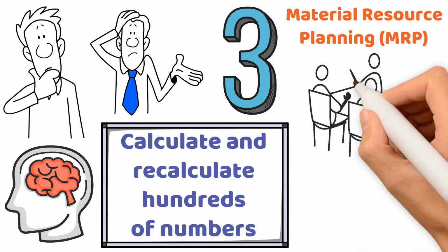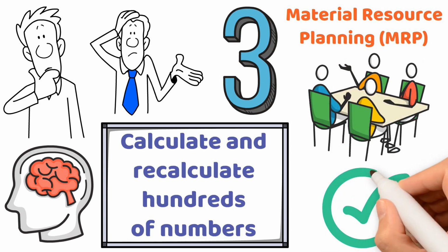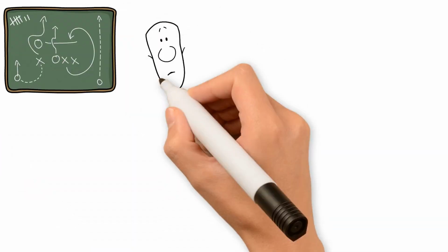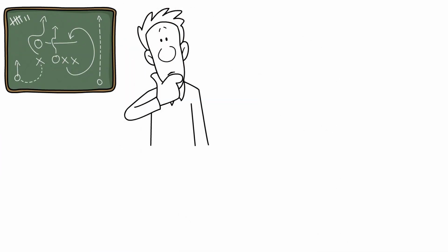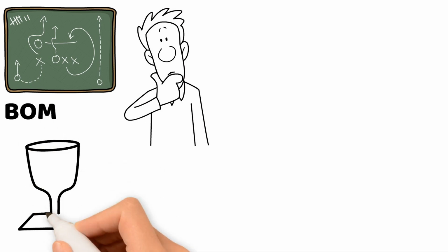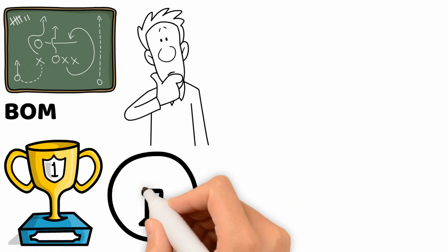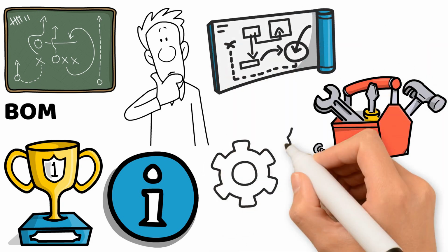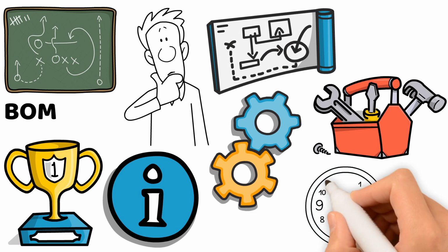Normally, a company has a demand forecast for a finished good, and this is entered into the MRP tool. This results in a production plan: what's going to be built and when. Because we already know the BOM and the lead times, we can enter the information in the MRP system. Then, knowing our production plan, the MRP tool knows how many parts we're going to need and when we're going to need them. It's simple.